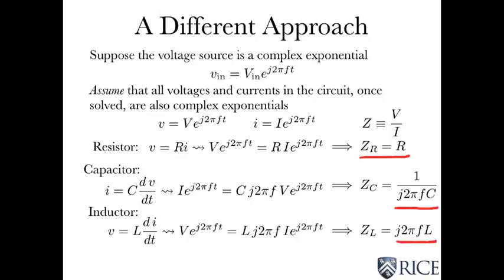So what this means is that we can think about every element in the circuit, resistors, capacitors, inductors, as being complex valued resistors, which is going to be the key thing. But we've now just checked the VI relations. We've got to check KVL and KCL before we figure out the consequences of that.